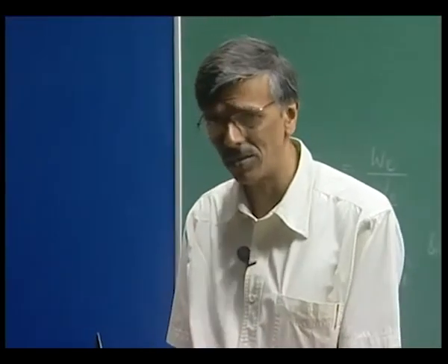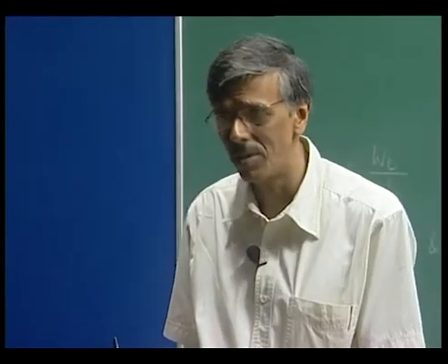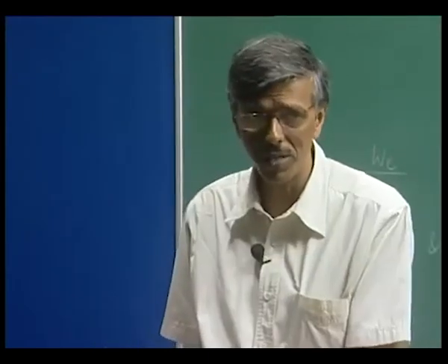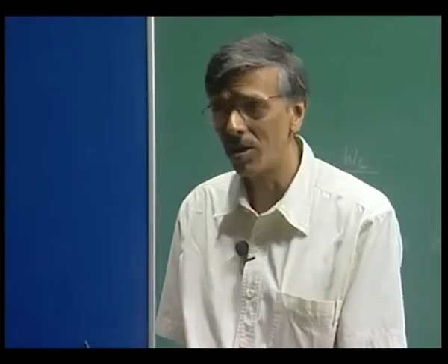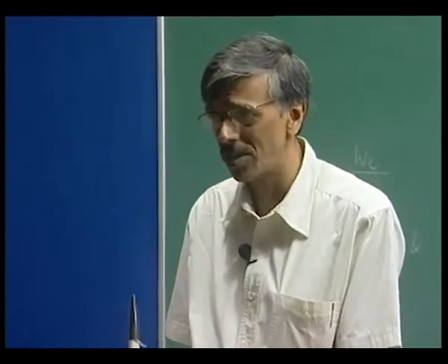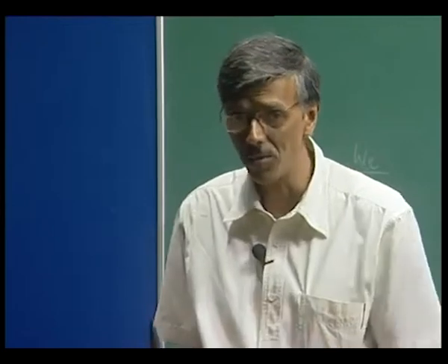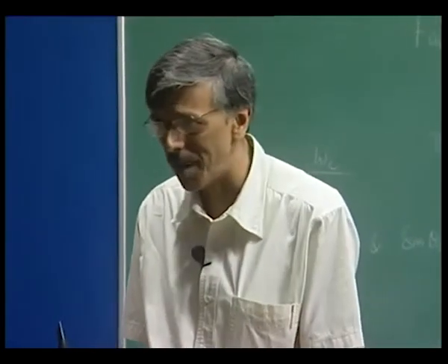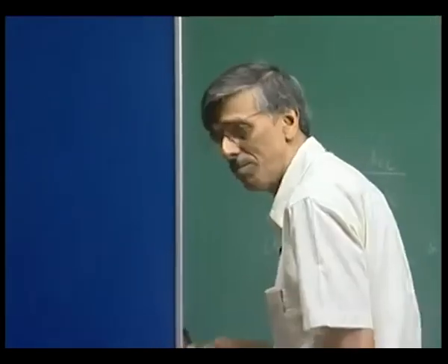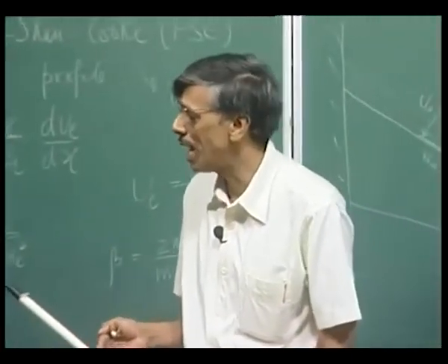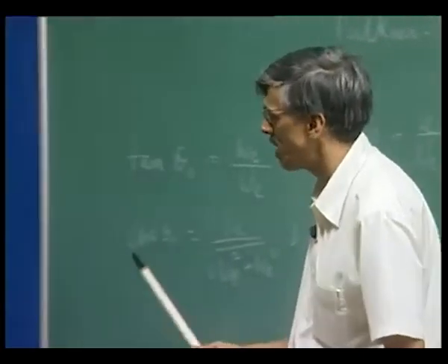It is much better than solving, let us say, the primitive variable and then converting those u and v components into vorticity, because there if I get a solution of a differential equation as u and v and then numerically differentiate to get omega, that accuracy will be compromised as compared to directly obtaining omega from a differential equation, right. So, that is what we like to emphasize.